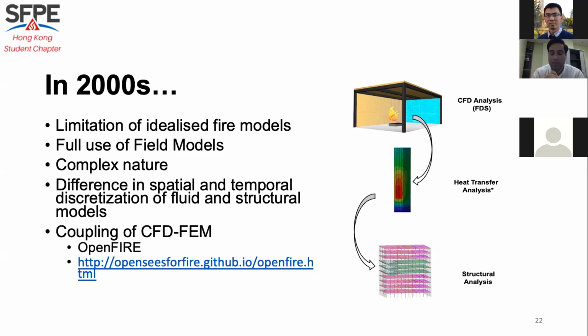But many models have been suggested by some researchers, and we also at PolyU try to couple FDS. FDS is a CFD tool which is developed by NIST. Sorry, I didn't mention earlier. So we connected FDS with another open source finite element model, OpenSees, and we were able to couple all these models.